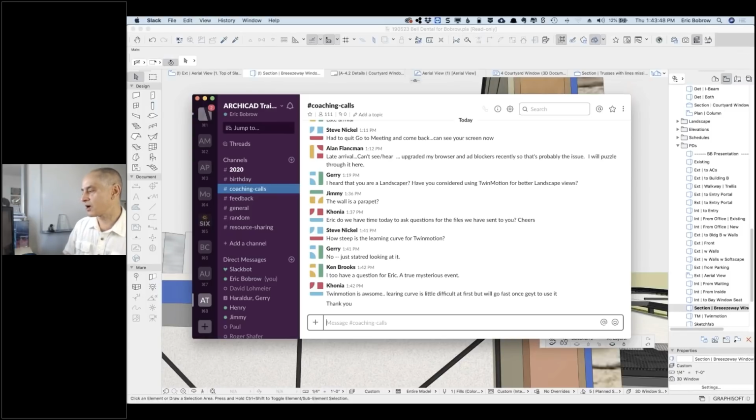Mackenzie says, how did you drag and drop the building material to update the priority? Did I use a key to help drag it? No, when you're in the building material dialog box, you can literally drag the materials around if you have them sorted in priority order. You can sort them alphabetically to find a material by name. But if you click on the header for priority, it will list them by priority, and you can just press your mouse down, drag, and drop it, and it will move into that position and change the priority so that it sorts numerically. So it's a convenient thing. You could also type in a new number and it would just move up or down, but dragging it is very intuitive.